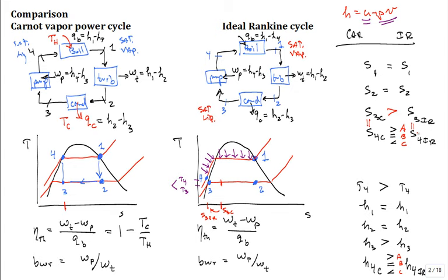I know that it's hard to draw it. Maybe on this one it's easier. I just say, look, it's on a straight line, same S, true? Over here, straight line. Well, okay, I didn't put state 4 perfectly above state 3 because it would exaggerate the temperature more than I can. So we're kind of bending the straight line up and down often when we draw it on the ideal Rankine. But, so the answer is the same as the previous answer, A. True? Okay.